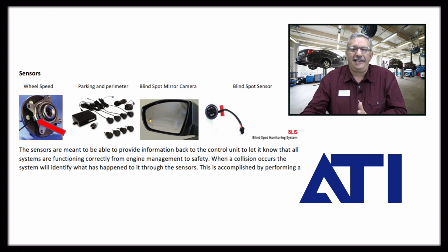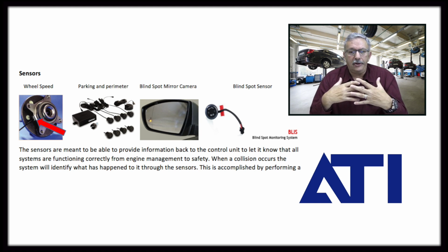So as we see these, there's lots of different sensors, and in one symposium I went to recently, Chrysler said that there were 150 sensor operations that the ALDL monitored when you plug the link in. That's a lot of systems that an insurance company will say, well, why do we need to check them all? Well, because number one, the manufacturer says so, and number two, there's no way I can visually inspect all 150 of those areas and know what they're doing. It takes a scan tool to tell us that.